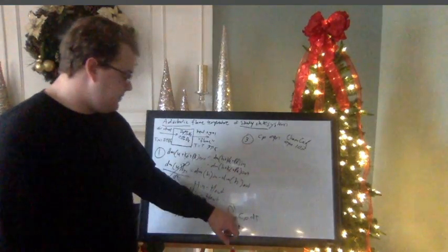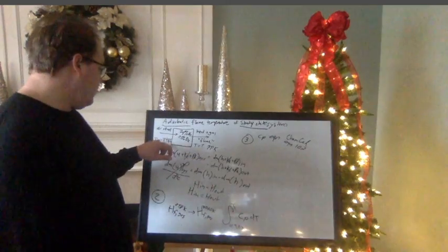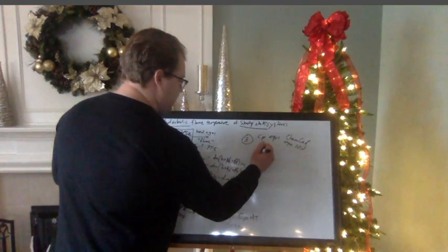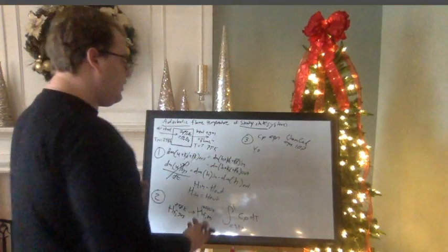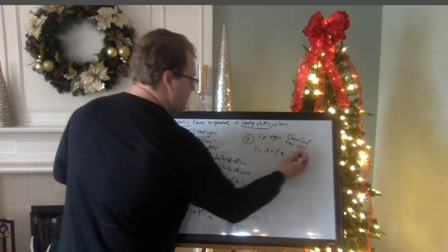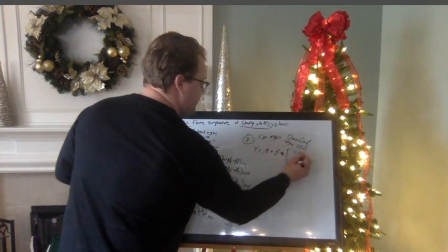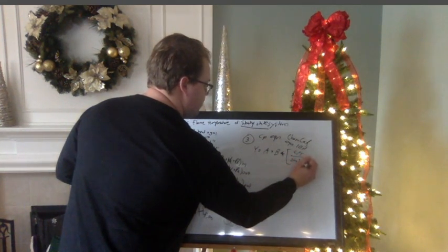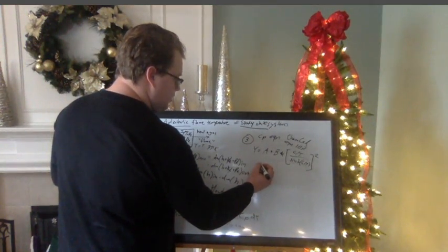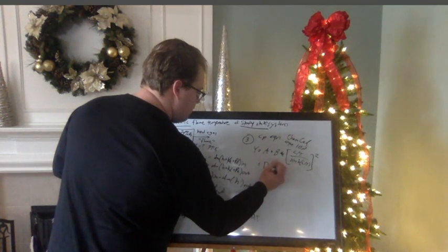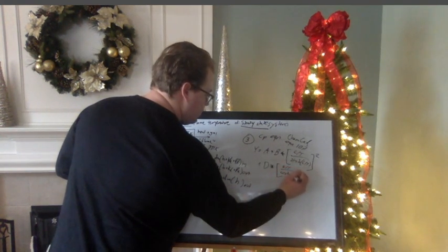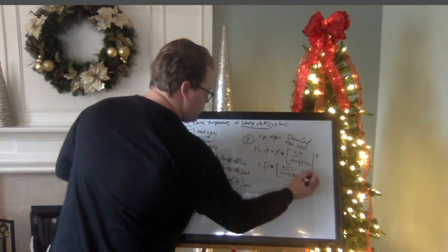And it's going to help us relate our specific heat of our air and fuel as it goes from our initial temperature to what we want to find as our final adiabatic flame temperature. So I'm going to write it out here, and I'll show it in the next part of the video as well. It's going to be Y equals A plus B times (C over T over sinh of C over T) squared, plus D times (E over T over cosh of E over T) squared.